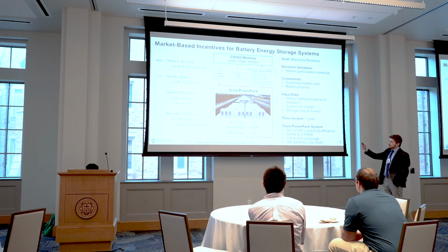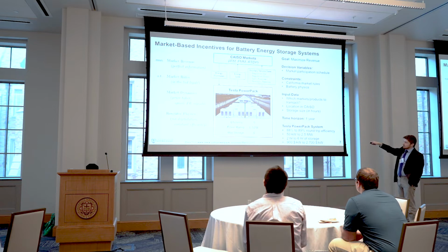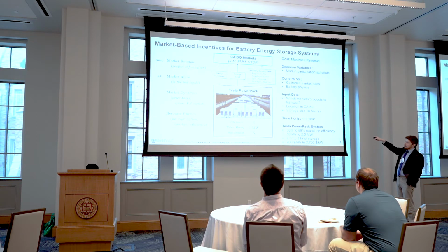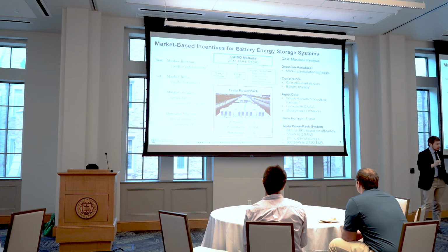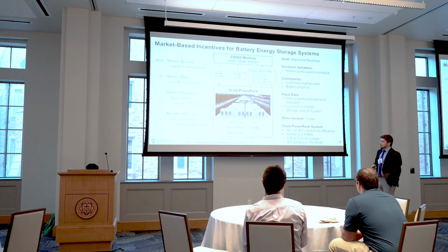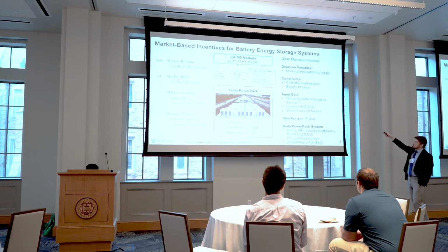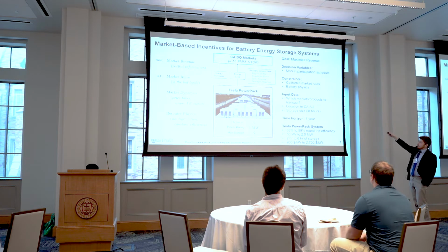So you can set up an optimization problem where you want to design an energy storage system, say a Tesla power pack, you want to size it correctly, where it can interact with the electric market in California, either buying or selling energy, or providing these ancillary services at the faster time scales to help balance the grid. And the goal is we want to maximize revenue, right? Because everything needs to be profitable.